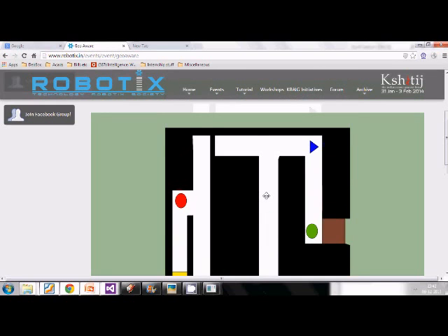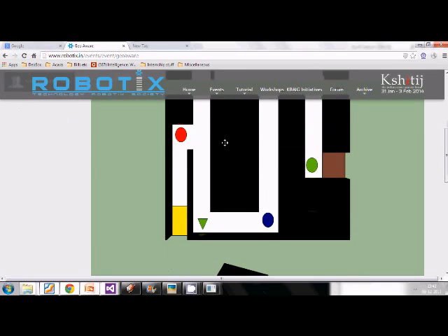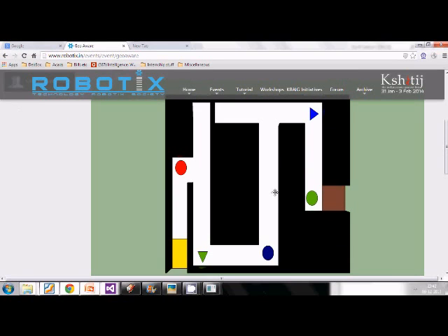We'll discuss tunnels shortly in the next module. You won't be able to notice tunnels by this. So you can do this if you want, but it will give you problems in round 3 as well as with tunnels. So a better idea would be to do lane following, reach the end, do shape detection, compare that shape with what you've observed from the map, and then take your decision accordingly.